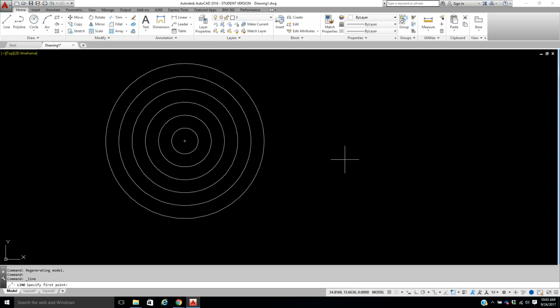It also works phenomenal when you've got something as a line, and say you need a line 1 inch away from there. Offset, 1, enter. You pick your line, you pick the direction. You pick your line, you pick your direction.